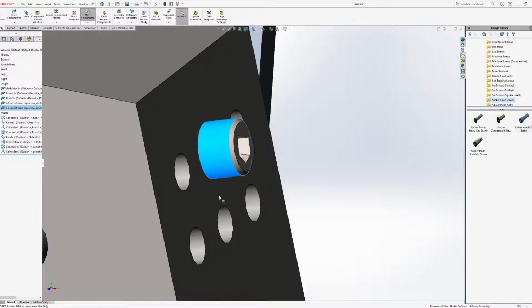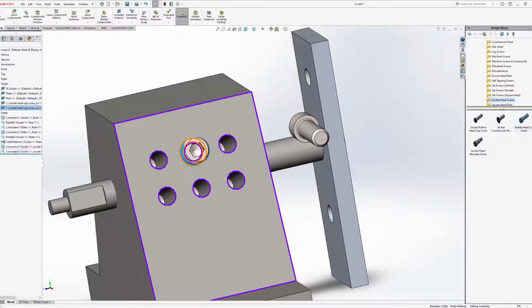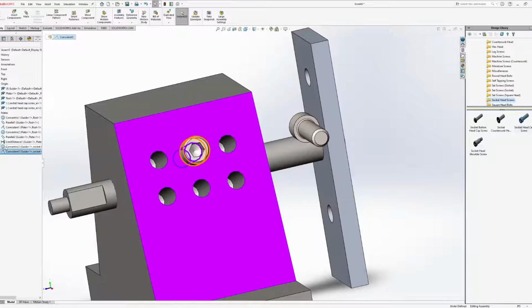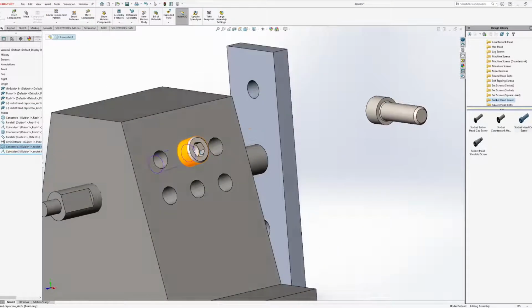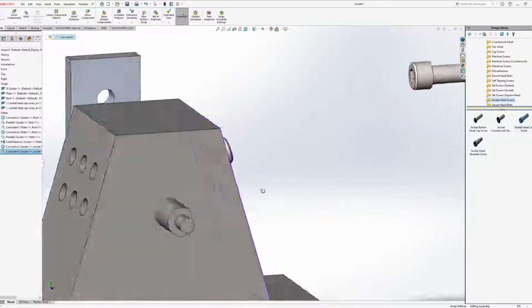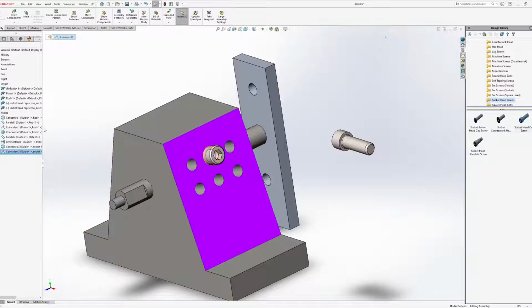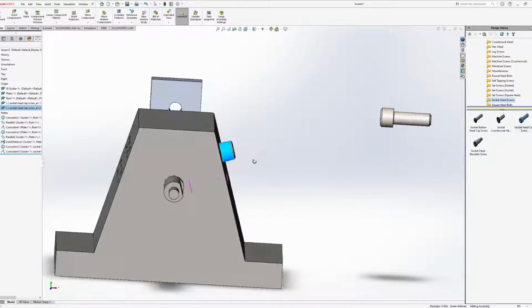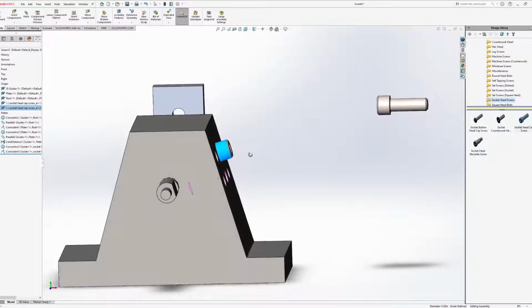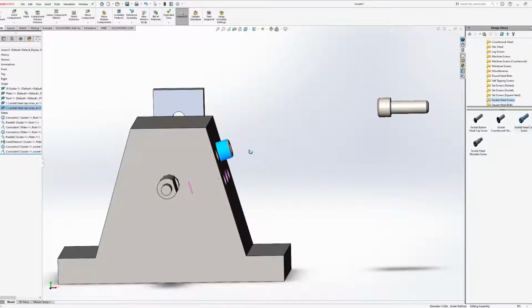It's only rotating, which means it already created not only a concentric to the hole, but a coincident as well to the surface. So sometimes that can help you, it can benefit. However, just keep in mind, like how we were talking about before, this actually is underdefined right now. Both of these are, based upon the fact that it does have that rotational degree of freedom. And technically speaking, I think that's rotating in like 2 degrees of freedom since it's at a slant.